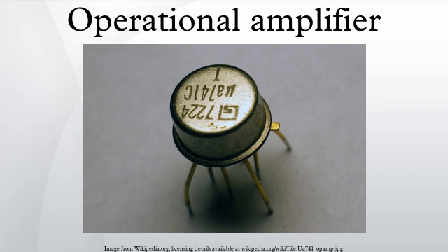Slewing: the amplifier's output voltage reaches its maximum rate of change, the slew rate, usually specified in volts per microsecond. When slewing occurs, further increases in the input signal have no effect on the rate of change of the output. Slewing is usually caused by internal capacitances in the amplifier, especially those used to implement its frequency compensation. Nonlinear input-output relationship: the output voltage may not be accurately proportional to the difference between the input voltages. It is commonly called distortion when the input signal is a waveform. This effect will be very small in a practical circuit where substantial negative feedback is used.